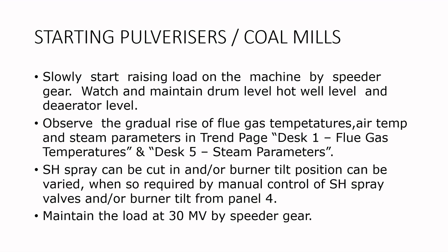The superheater spray can be cut in and/or burner tilt position can be varied when so required, by manual control of superheater spray valves and/or burner tilt from panel number 4. Now in this, suppose you take the elevation, instead of coal mill A you take coal mill E in service or coal mill F in service, then you may face this problem that superheater temperatures are increasing, so the superheater spray can be cut in.